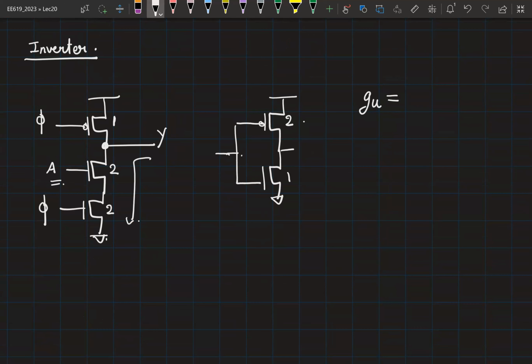And here, when we were using a pseudo NMOS based logic, you also had to worry that your logical effort associated with the pull-up network was getting worse, right? Here, if you are comparing the delays in the evaluation phase, the delay in getting to VDD is basically 0 because you're simply holding the value there as it is. So repeat the same exercise for NAND 2.